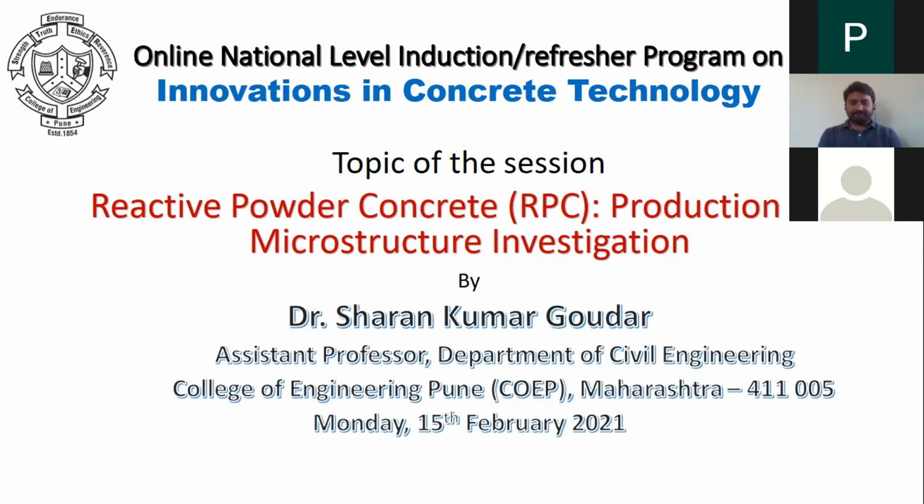Before I move on to the production and microstructure investigation, let me introduce the topic first: reactive powder concrete. We'll divide that into three parts: the reactive part, the powder part, and the concrete part. I'll focus on the middle part first, that is powder. What do I mean by powder? All the materials which I have used in this concrete are in the form of very fine materials, so that's why we call them powder. As you saw in that video, there was no coarse aggregate at all. We have completely eliminated the coarse aggregate while producing reactive powder concrete, and most of the material is in the form of powder.